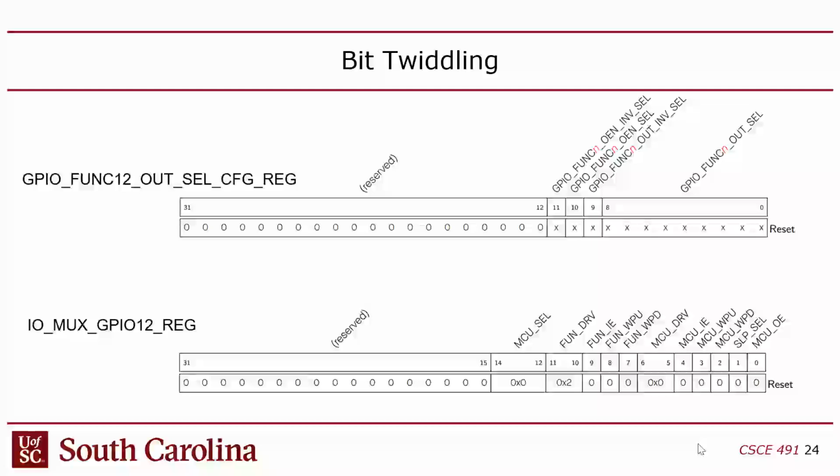And then the other mux, the I/O mux, has a little 3-bit field over here that you have to set, right? The problem is all 40 pins have a different interpretation of what the I/O mux select does. So then there's another table in the technical manual that you have to look up for each of those pins. So depending on what pin you want to set up, you have to look up its specific I/O mux setup. You guys with me? So this is an example of how you would have to write code to set these fields to achieve a certain goal.